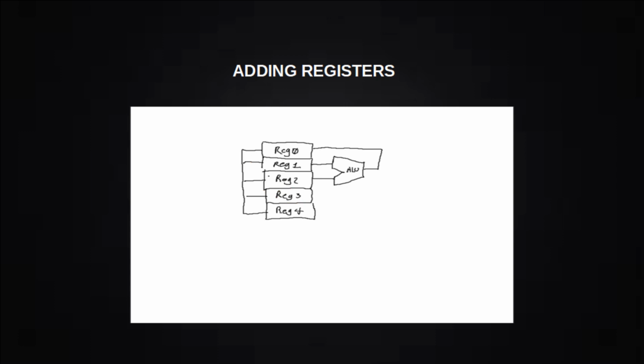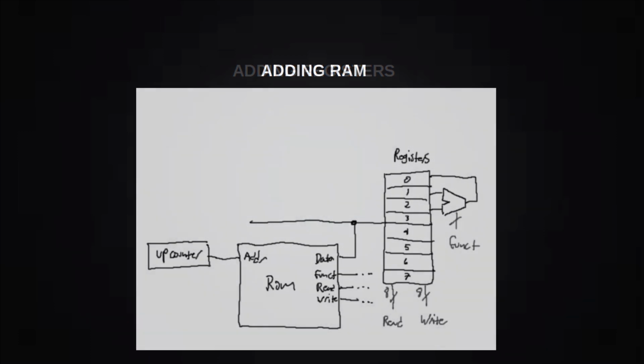This simple architecture shows how everything moves through register 0, and that operations only happen with registers 1 and 2. This sort of computer architecture is advantageous for its simplicity, but performing any meaningful operation will require shuffling registers around. So again, you have a trade-off of hardware and software complexity. Similar to the problem of sequencing adders, if you give your computer a certain number of registers, you're almost guaranteed to eventually encounter a program that will exceed the number of registers that you have.